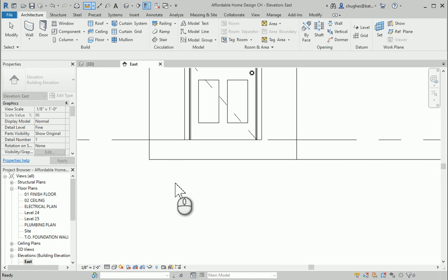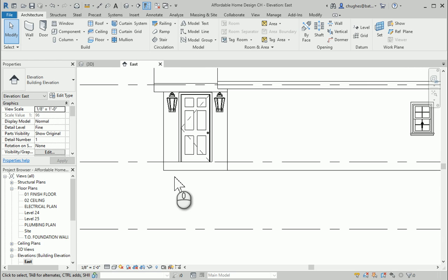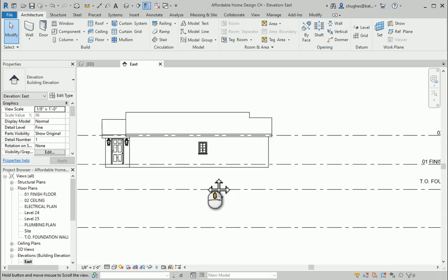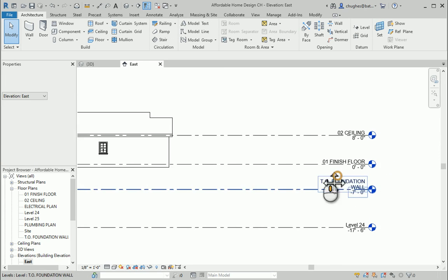So when we look at setting this up, I've got 10 3/4 of an inch, but I need to add the height of that 2x6 laying down. So I need to add another 1.5 inches. 10.75 plus 1.5 is going to put me at 12.25, or 12 1/4. Here's what I'm going to do to help me out with setting this up.